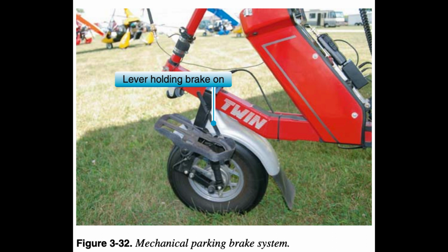Figure 3.32. The main landing gear is the two rear wheels of the WSC aircraft. Since the center of gravity, CG, is much closer to the rear wheels, most of the weight for the aircraft is carried on the rear wheels for taxi, takeoff, and landings. There are a number of different configurations for the main gear. A conventional configuration has two separate systems for each rear wheel. Each side is two structural triangles, one horizontal and one vertical.